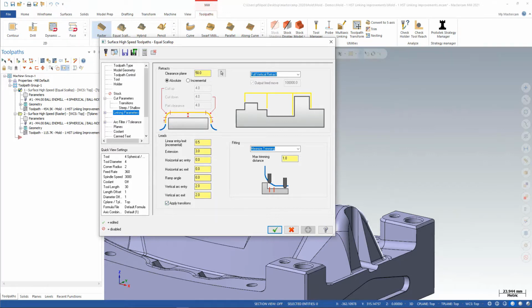And if you're ever in these toolpaths getting bad results, make sure you look at these numbers here. Some of these need to be lowered or zeroed out to get really what you're after. Otherwise, you may be getting some big lead-ins and lead-outs in there. So definitely take a look at it. That's an awesome fix there that they did, or enhancement, I should say.